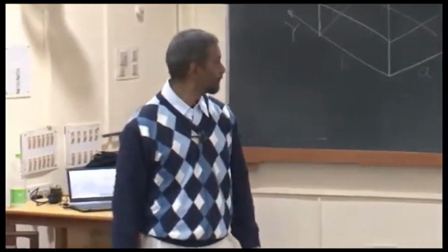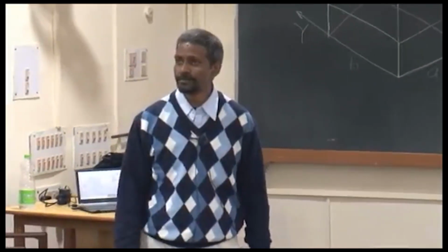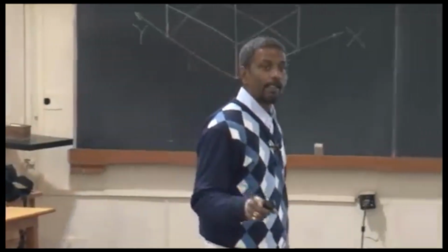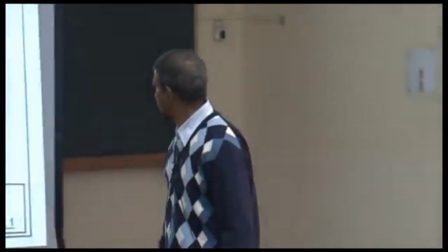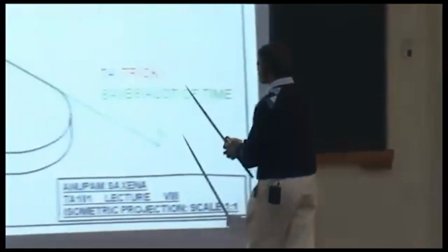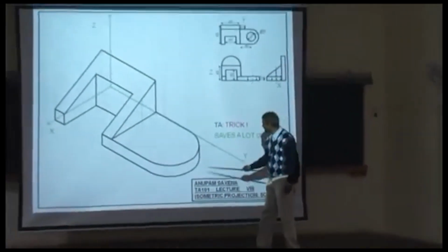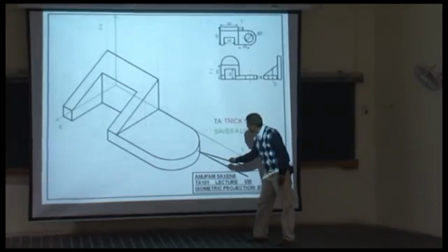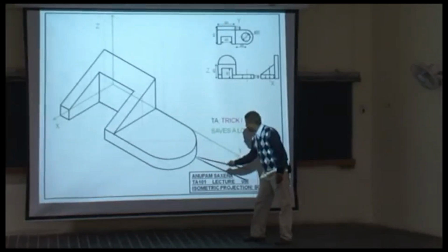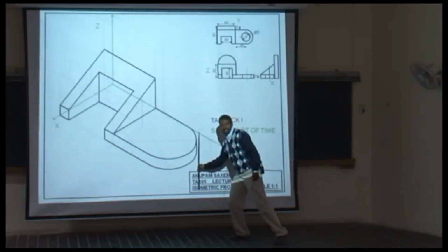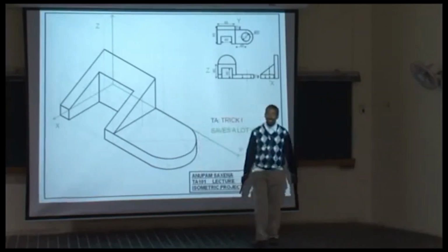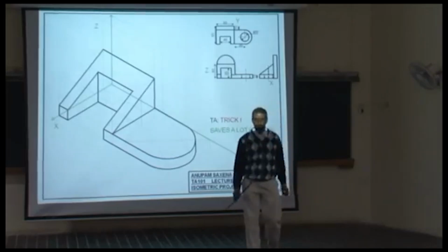So far so good? While drawing the second arc at the bottom, where will you decide from where I should draw the vertical line? It has to be tangent to the arc. So if you draw this arc using soft pencil, using construction lines, your arc will probably go somewhere like this, and the point where the vertical line intersects with the arc, that is where you need to stop.